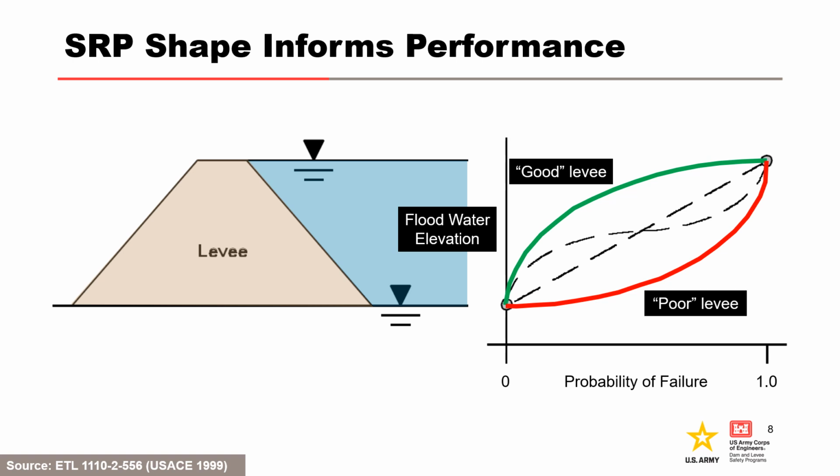The actual curve may be closer to an S-shape or intermediate curve, which is similar in shape to the good case for small floods, but reverses to approach the poor case for floods of significant height. A straight line function is also shown, representing a linear relation between reliability and flood height. Linearity would not be expected to be the general case.